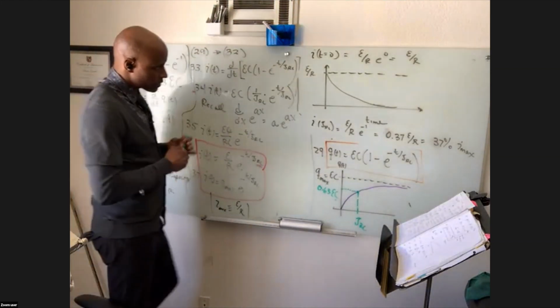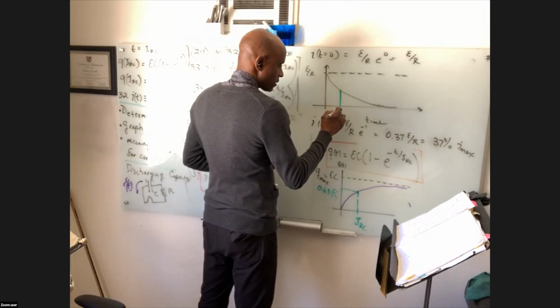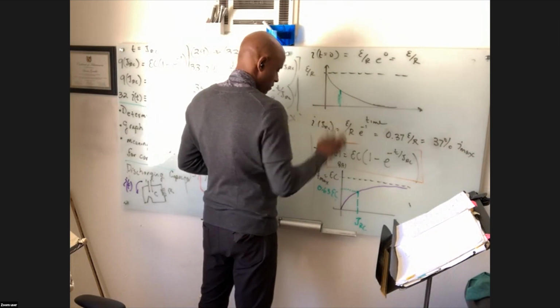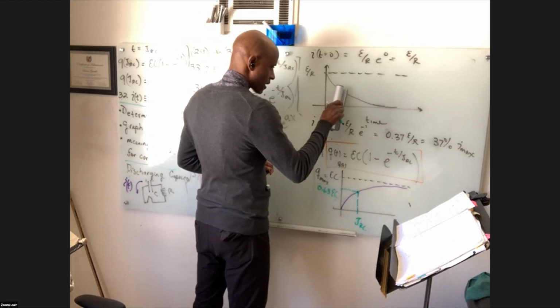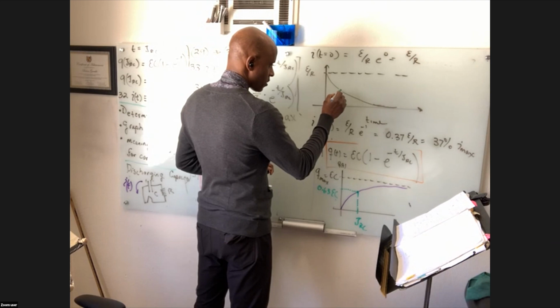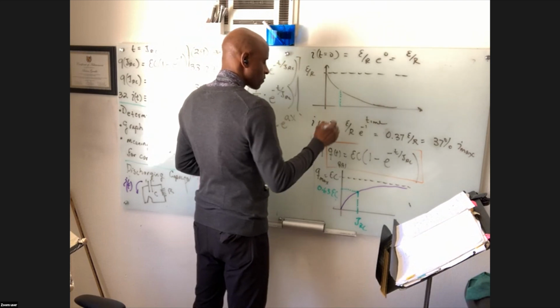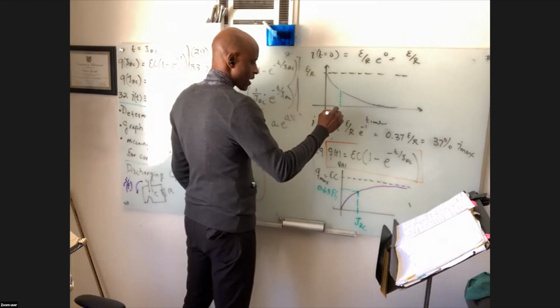Again, it gives us some qualitative gauge of how long it takes this thing to discharge. Because if the time constant is 10 seconds, then in one time constant the object has discharged to 37%. So in 30 seconds or so, you could assume that it's practically discharged for that example.